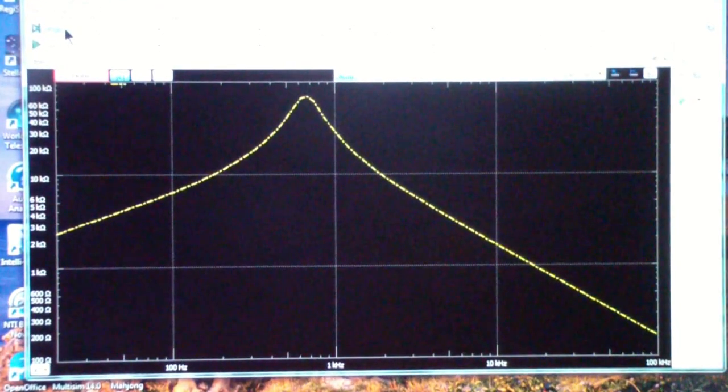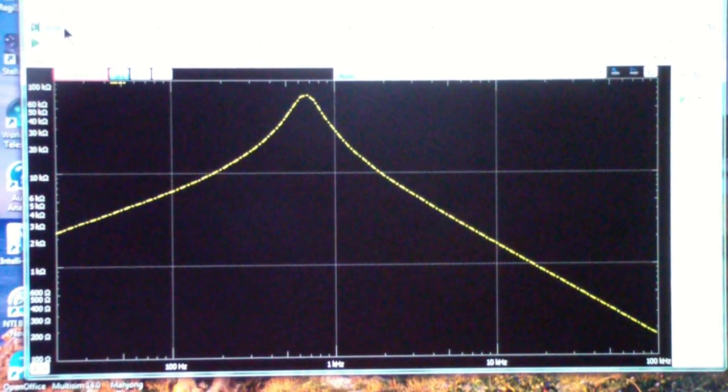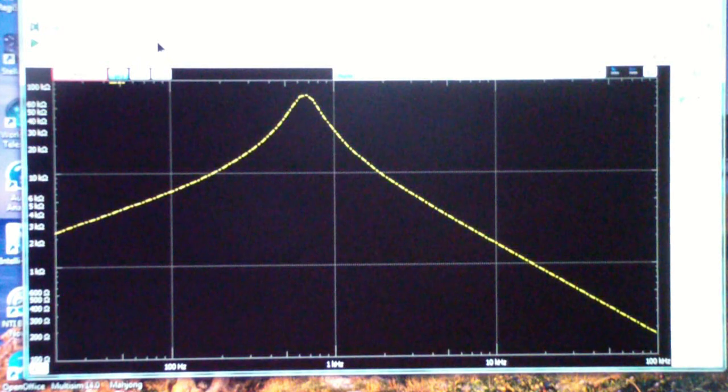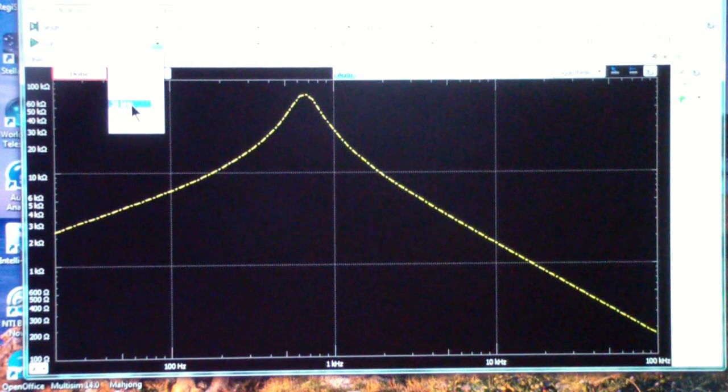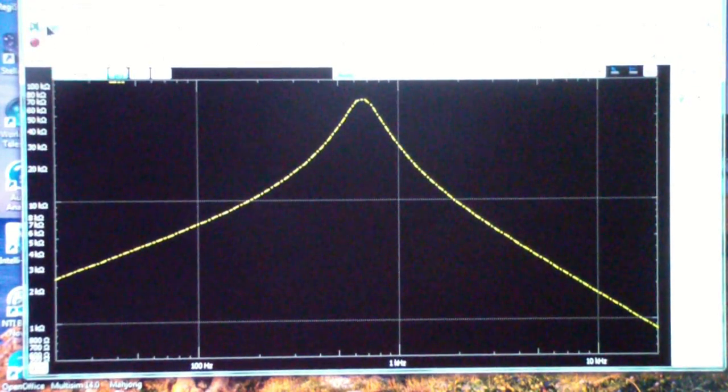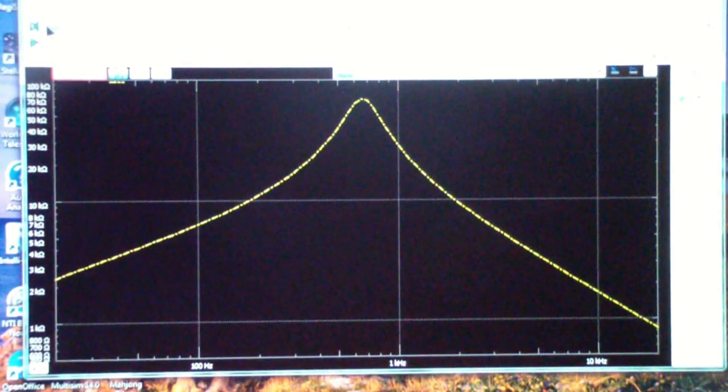Now, in terms of actual audio frequency, one reason I'm using 100 kilohertz is just to show you what happens at the very high frequencies. We could also go to just 20 kilohertz here, and we'll run that and see what it looks like. This is, of course, the normal audio range. Okay, now let's go back to the 100 ohm resistor that did not work in the resistor first case and run that.